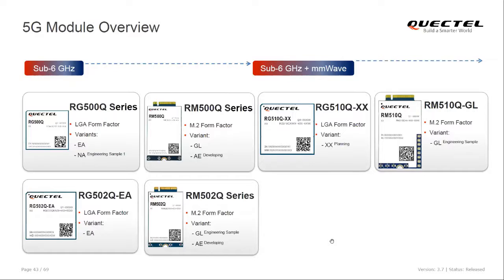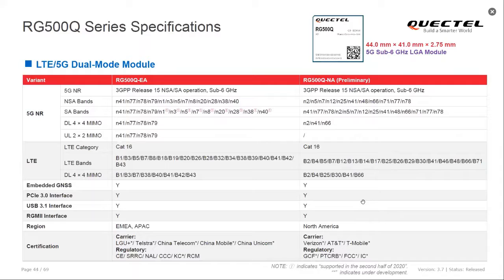One of these is for GNSS, so only 3 for LTE, while millimeter wave has many more antennas. All of these are M.2 form factor because this form factor supports high speed over USB 3.0 or PCIe interfaces. In the next slide, I have more detailed info.